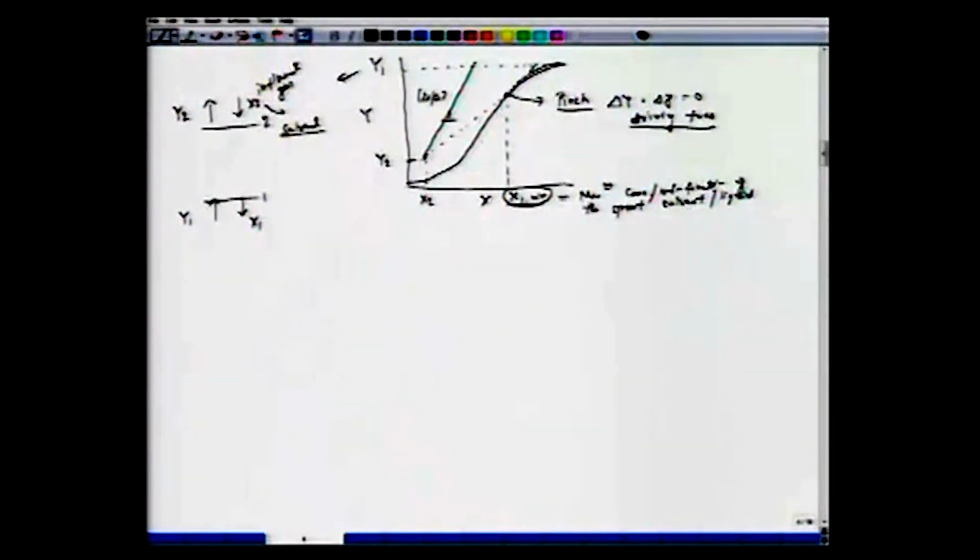All right. So if we take the slope here, this will correspond to Ls by Gs minimum. In other words, if we decrease the liquid amount or liquid flow rate, then the operating line will move in this direction till it makes a tangent here.